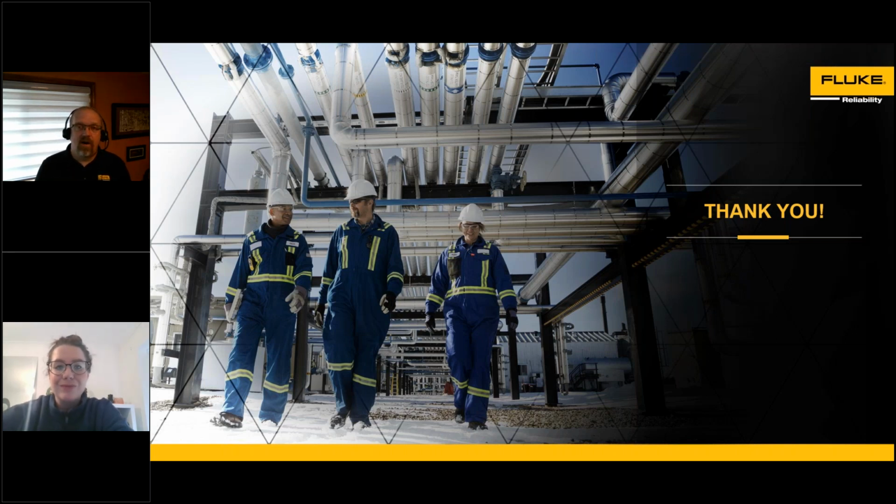If you're looking at a more complex machine, you'll want to make sure that you're taking data at the right point. Data can be skewed by taking data in an area where you are seeing multiple components with the same sensor. So you want to do a survey and make sure that you're installing your system where it is appropriate and you're installing the right size system, not underselling it, not trying to get by with too lean of a monitoring program, and monitor completely and thoroughly.